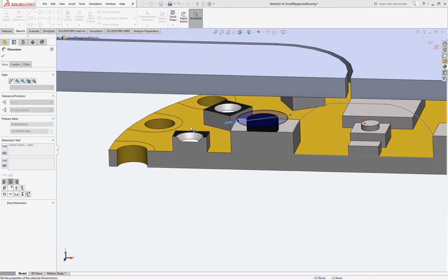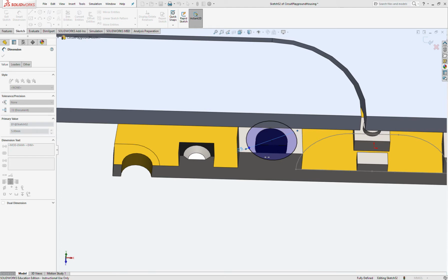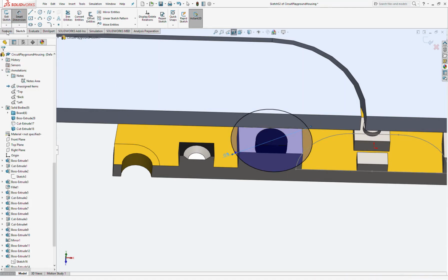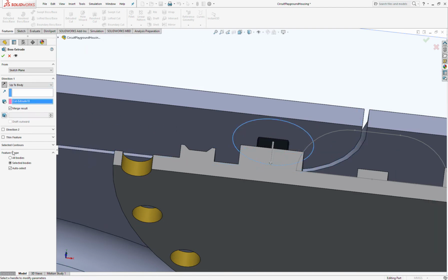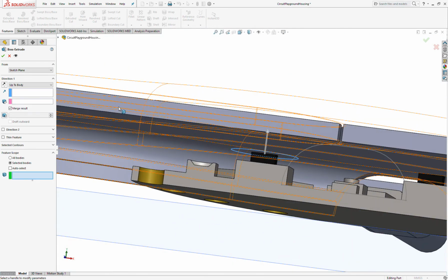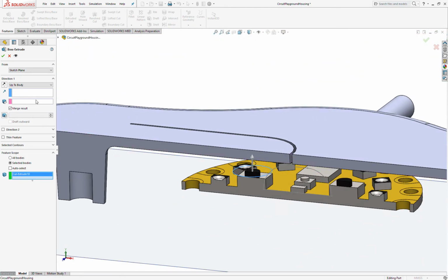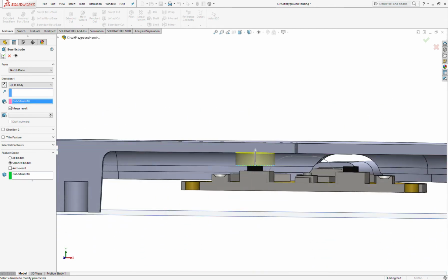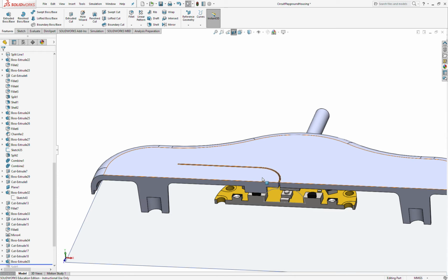In this case, I'm going to make this pad reasonably large, but I don't want to obscure my LEDs. So we'll go with 8. Go. And we can extrude this up to the body. Merge the result with that. With this. There we go. Perfect.